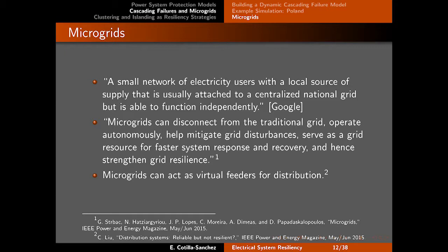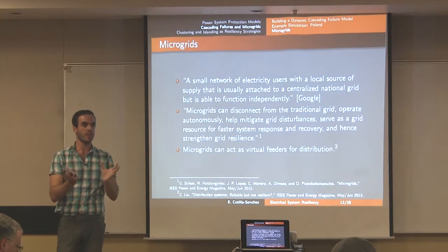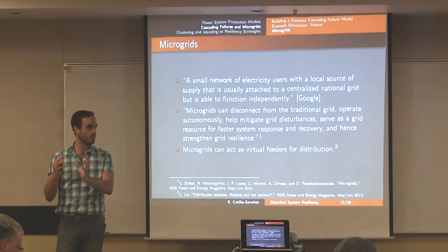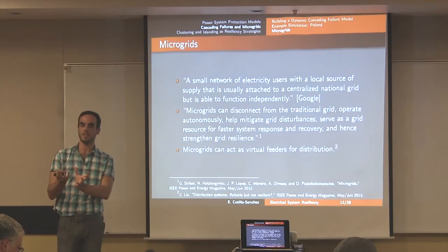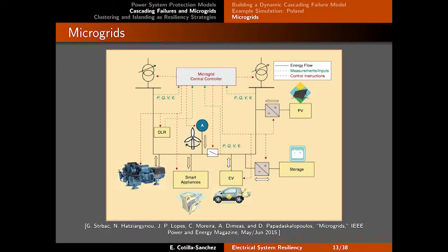So really, when we are looking at resiliency or big event applications, we are looking at those transitions between grid connected and going to a microgrid, because that will give you a large percentage of load that survives, perhaps. This is just the complexity of what you will have to put in the model for a microgrid. Imagine that we're talking about how to put in that model a lot of the relays, a lot of the different elements that you will have just as a regular substation.